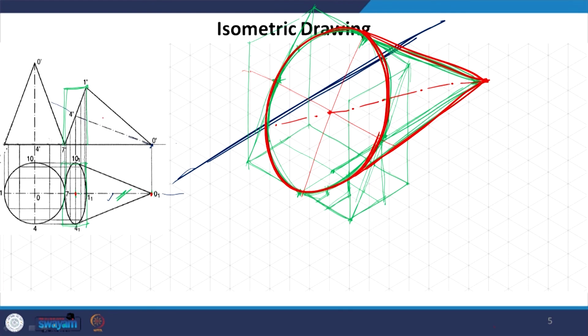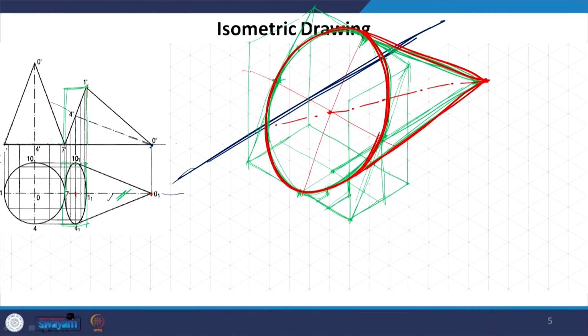We know the reference rectangles, how to draw these reference rectangles, but reference rectangles can only be drawn for planar surfaces where we know what that plane is which we are talking about. So, we can create these reference rectangles for the same plane. Now, you can't create a reference plane for this conical part because it is not a plane, it is a 3D surface. However, we can do that if we were talking about the pyramids.